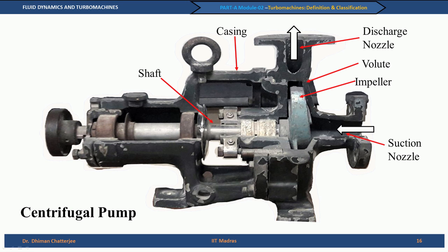We also have a deflector. You can see this plate ring which is given. So, the deflector actually deflects any amount of water that has come in, so that it does not go to the bearing housing and to the subsequent downstream part into the motor.